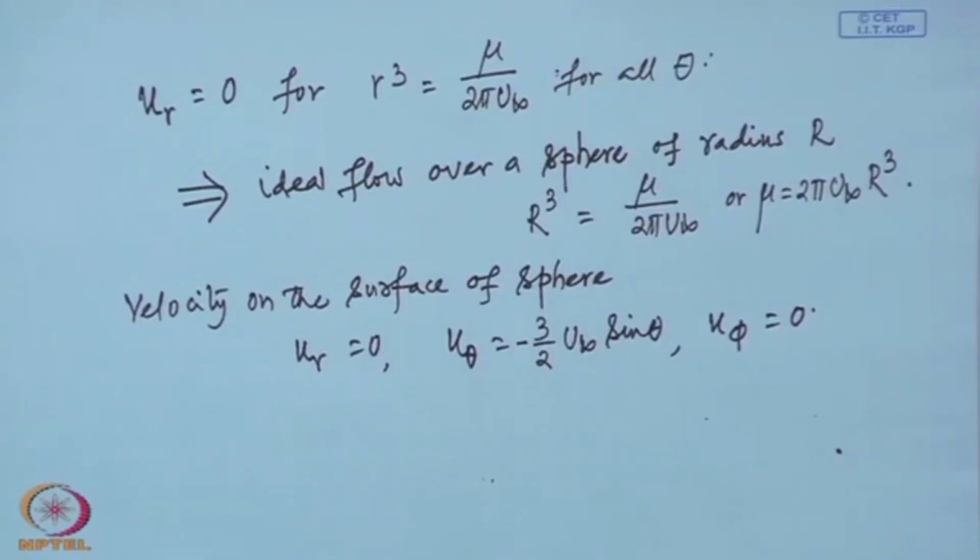So, at theta equal to pi, the flow velocity was 0 and it increases to 2 U infinity in case of cylinder, while it increases up to 3 by 2 or 1.5 U infinity in case of a sphere. So, flow has accelerated less, and that will be reflected of course in pressure also. If we look for the pressure coefficient, what it will be?